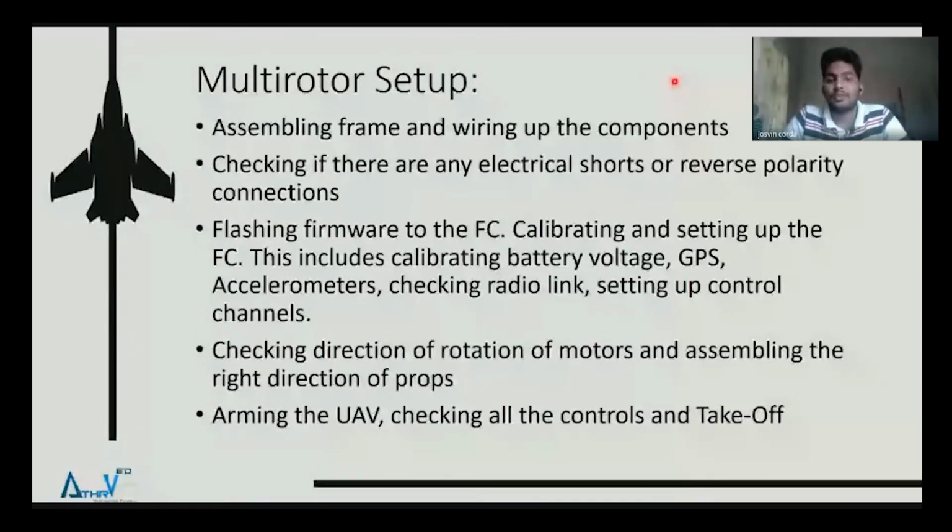Like if you pitch up on the radio, whether the same input reflects on the FC. Then you have to set up the control channels. There will be many switches on the transmitters. So for each of the switches, you can add a function, like if you move one switch, a payload may drop.